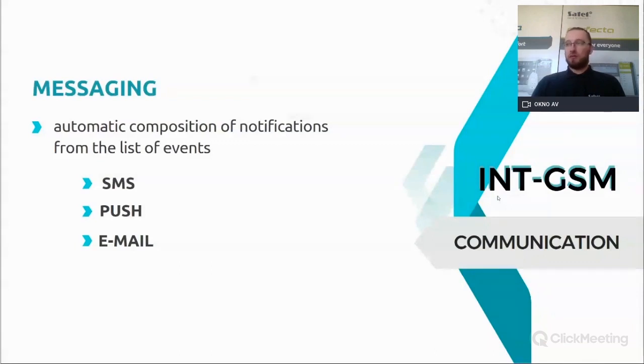So you don't need to create, for example, if your clients require that you want to receive notification who armed or who disarms system every day, and you have, for example, 100 different users in Integra panel, you don't need to specify every single SMS. You just mark option arm disarm status and partition 1, and you will receive all the information from there without any additional configuration from your side. This helps to save a lot of time.